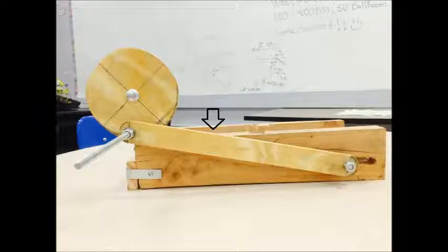For our stress calculation, we assumed that the coupler and the 2 bolts attached to it would be under the most stress. Therefore, we calculated the buckling of the coupler and the bearing stress for the 2 bolts attached to it. Knowing that we had a long, slender coupler, we knew that buckling would be a major factor in our calculations. In the end, we used Euler's equation to calculate the stress at which buckling would occur.